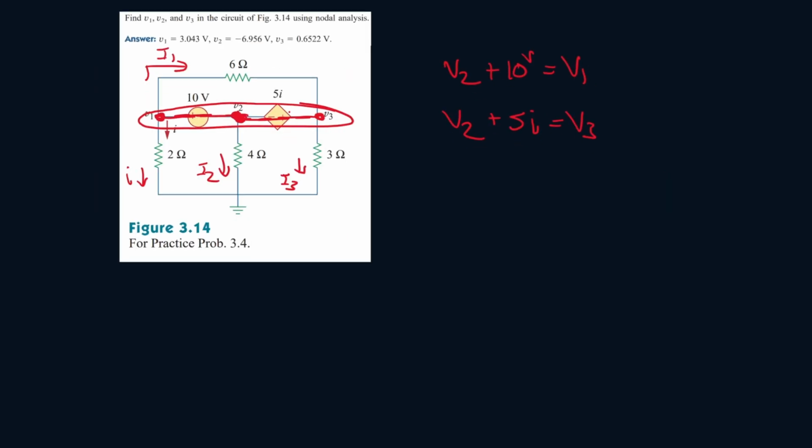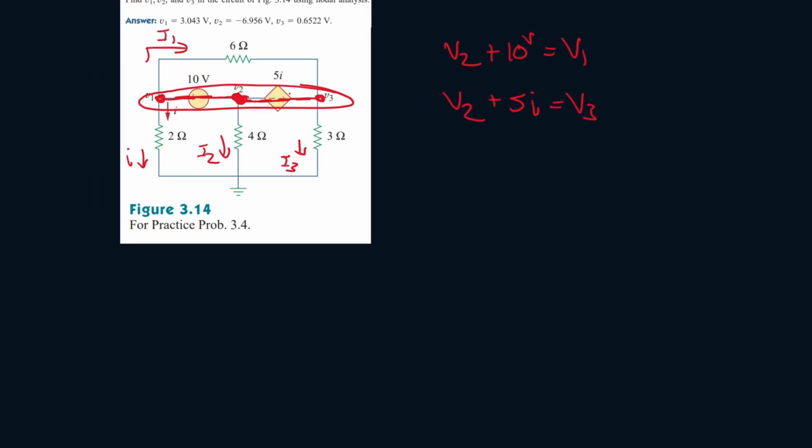Okay, so let's write the equation. So I1 is leaving plus I plus I2 plus I3, and there's also I1 entering from this portion, so I1 is entering, and then we can see that the I1s cancel out, so it'll be just 0. I plus I2 plus I3 equals 0. Now let's figure out these I's.